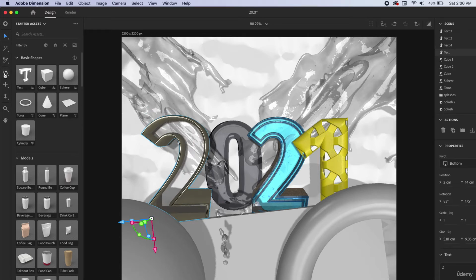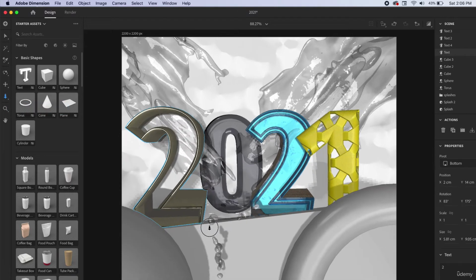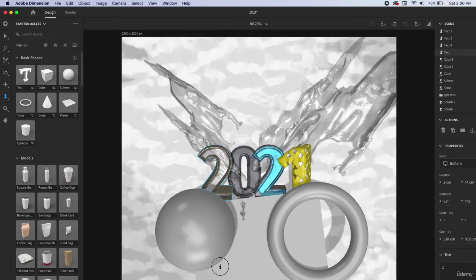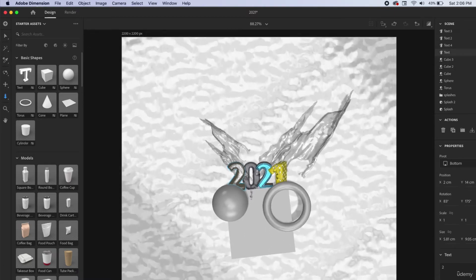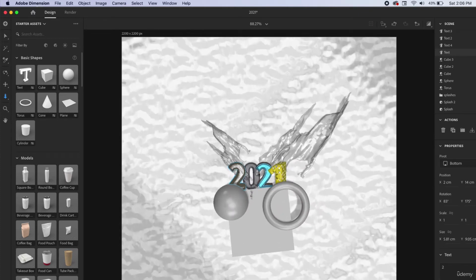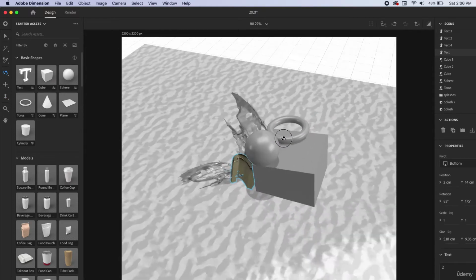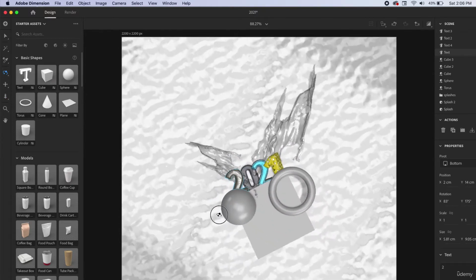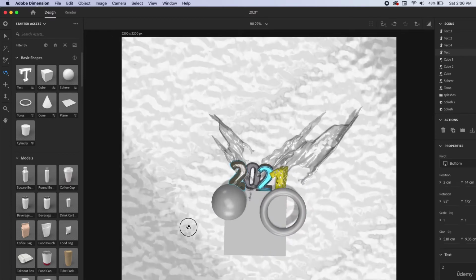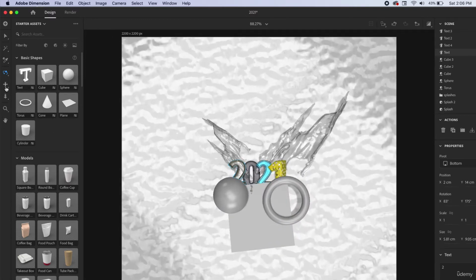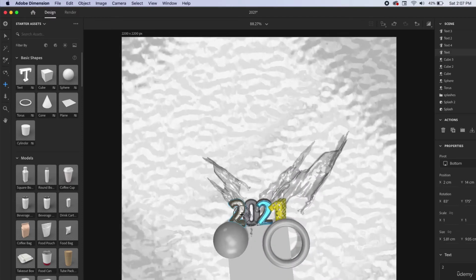And then you have all your camera angles. Camera angle is going to be different. It's not going to change the position of the 3D object, but it's going to change your view of the project. This is dolly, so I'm going to dolly out. If you're used to camera work, it has the same terminology. So we're going to dolly out, and you can see the entire artboard here. And then I can orbit. I'm just going to orbit around, and this is how you set the angle and the view of your final render, which is sometimes just as important as the objects themselves. And then lastly, we have pan. Pan is going to pan around the object.